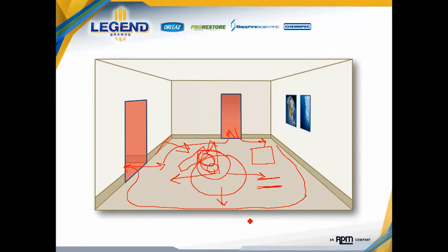So as a summary, it's critical that we generate air movement across every one of the target wet materials that we're trying to dry within the space. That is best installed or assured by ensuring that we strategically place air movement to ensure that we're moving or transporting air throughout the entire drying space.